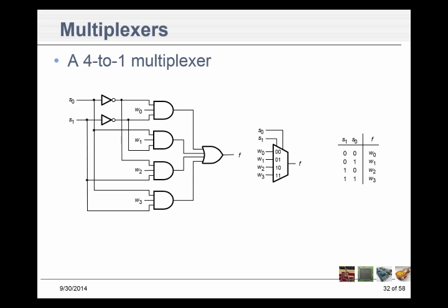Now, remember back to your homework. You guys were wondering, why did I give you that table that had A, B, C, D that counted from 0 to 15 and W, X, Y, Z that had all kinds of numbers in there? What was I doing? Any idea? A, B, C, D was supposed to be the selector bits to a 16-input multiplexer. The W, X, Y, or Z were the output for the multiplexer. And those inputs were in the table. Okay? So then we could spell that out on this multiplexer as a summation expression. We could spell it out as a VHDL expression or minimum SOP expression or anything like that.